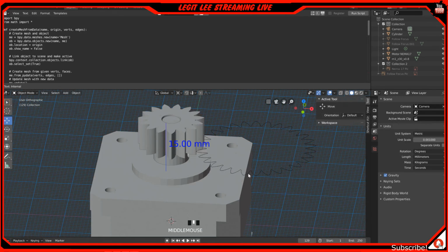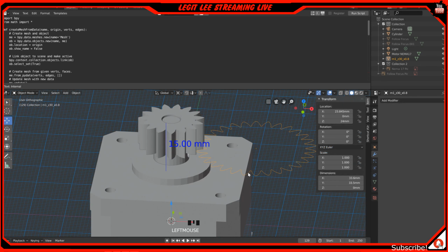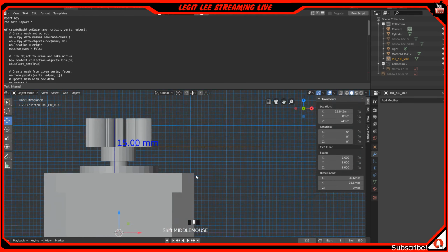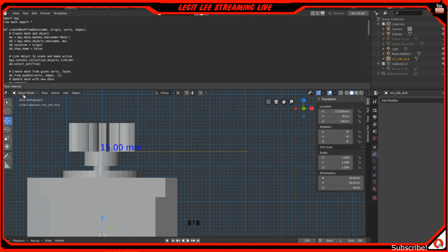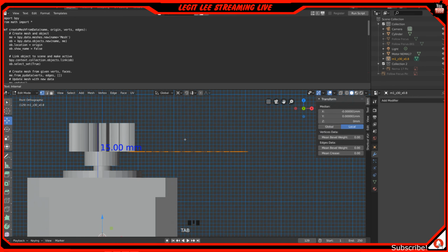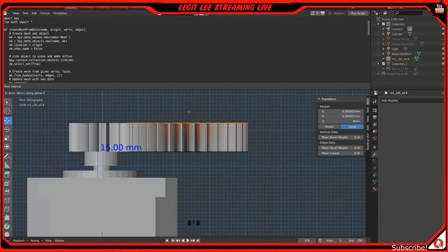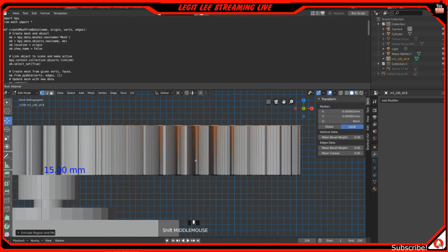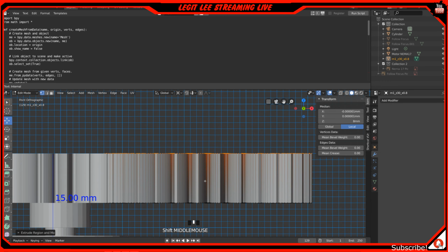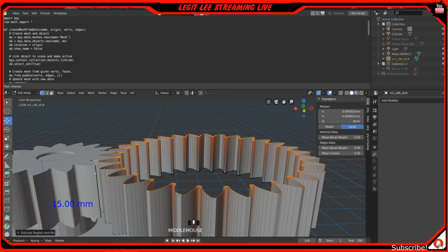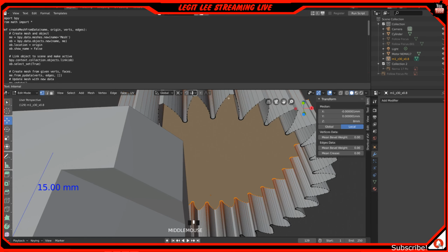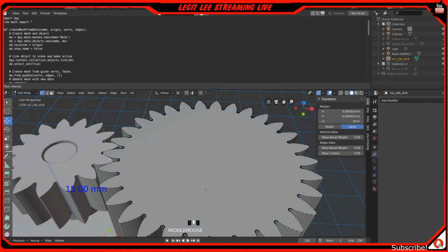Now we'll go ahead and click on this one. We can get started on this guy. So first we're going to go from object mode to edit mode, and then we're going to do another extrude on the Z, pull it up 1 2 3 4 5 6 7, basically it's like 8, I guess. We know for sure it's 8 because it's matching up with this one. I just don't know why. Anyway, F to face, click on this guy down here, Alt left click, and then we're going to F to face again, just like how we did this one.